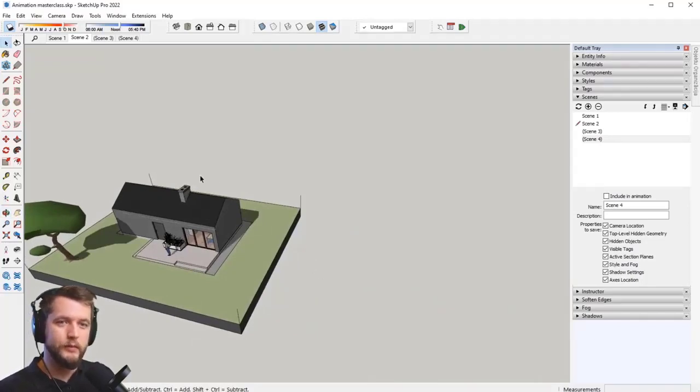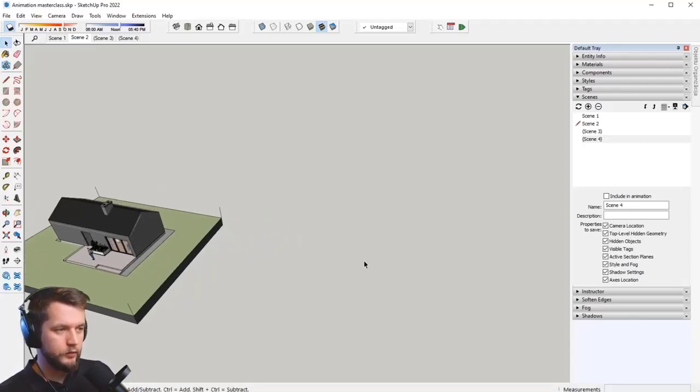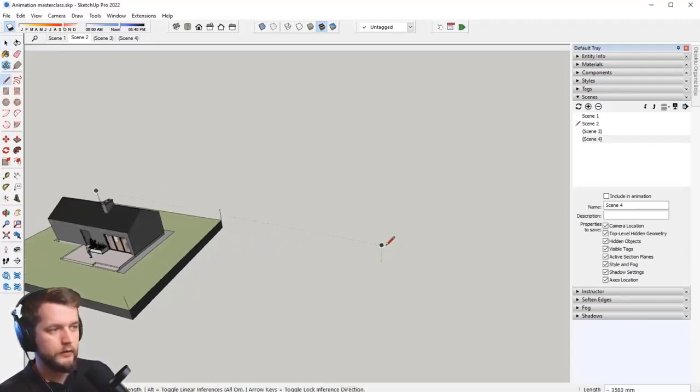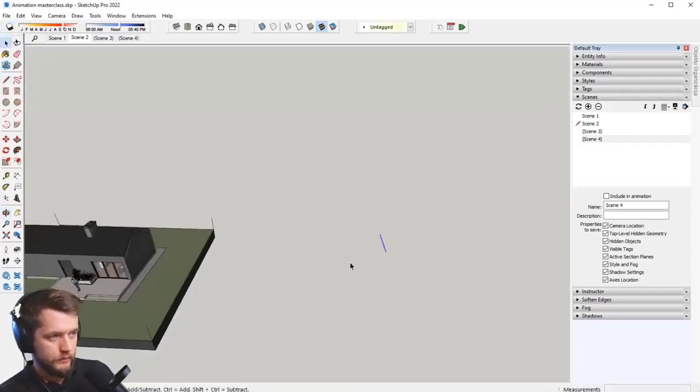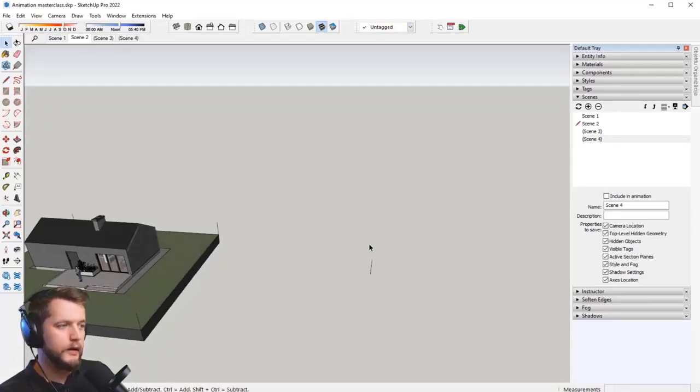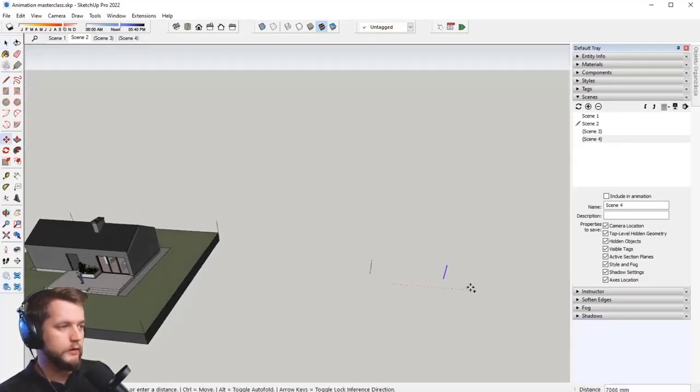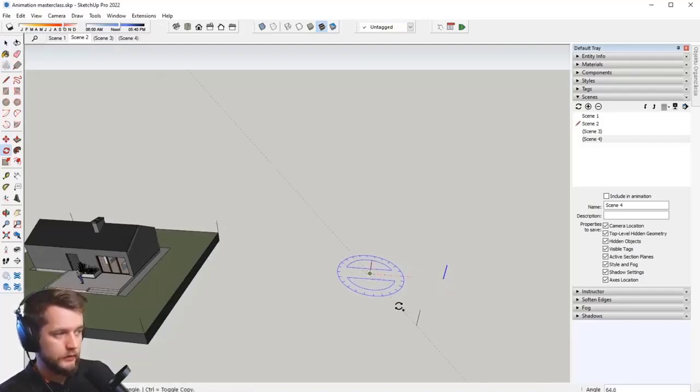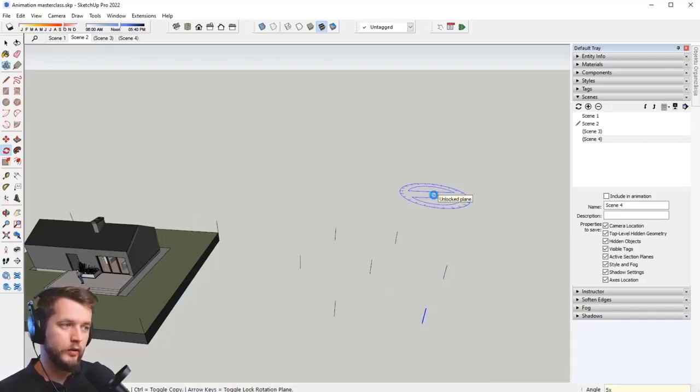And for animations where I want to be a bit more precise, maybe this rotation around an object, it would be useful to draw, for instance, one line. That's going to be the center line, let me draw it straight up, and then I could draw another. Using the rotate tool, I'm going to rotate it, say to 60 degrees, and press 5x to copy it around.